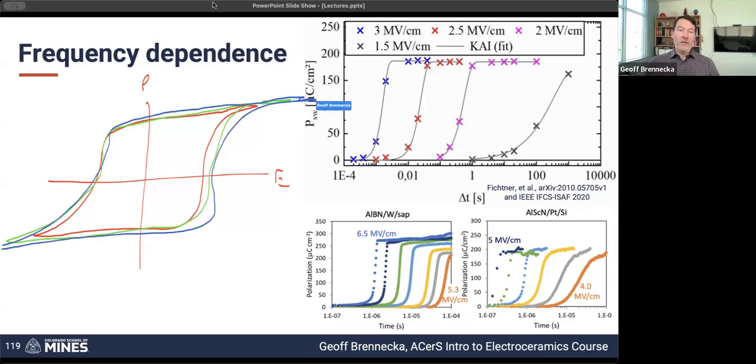So you can measure the exact same frequency, but just go to a higher maximum voltage each time. And if the coercive fields and remanent polarization values line up fairly well as you increase the voltage and/or change the measurement frequency, that's a really good indication that what you're measuring is the actual domain response of the material and not being dominated by loss.